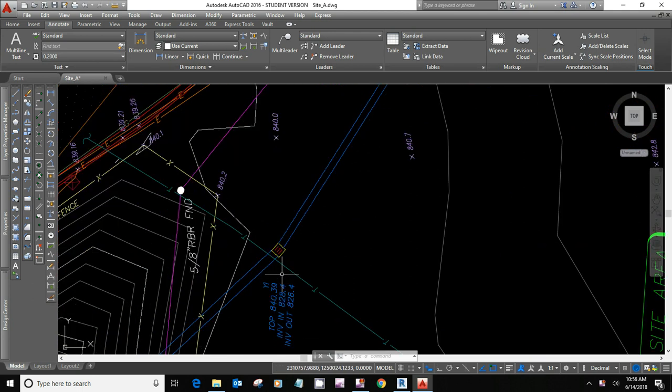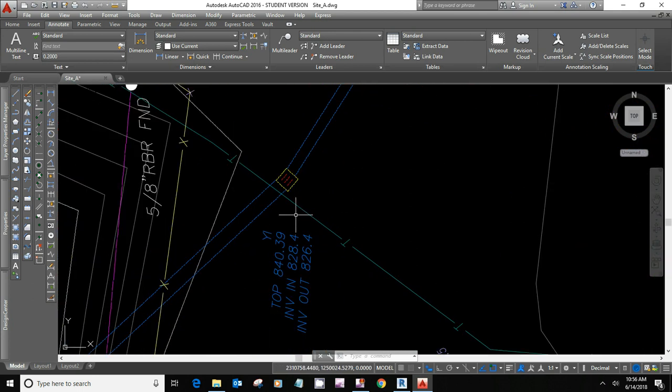Here at the catch basin, we do know some elevations here. Okay, and it might be easier to go ahead and do the math and write these things down here. So our finished floor is at 844 feet, level one, and that's where we're going to insert these things.